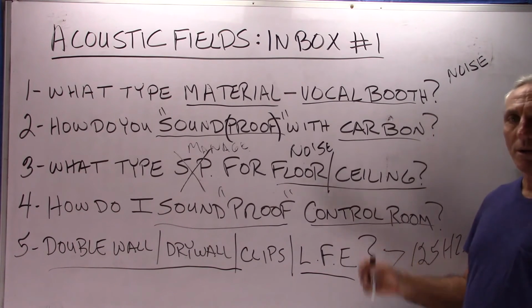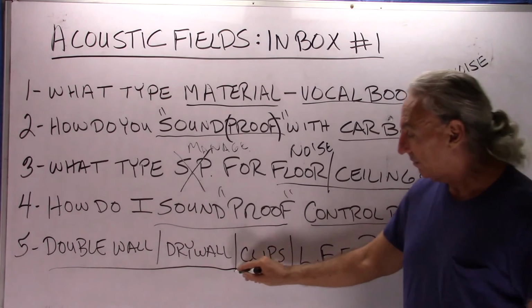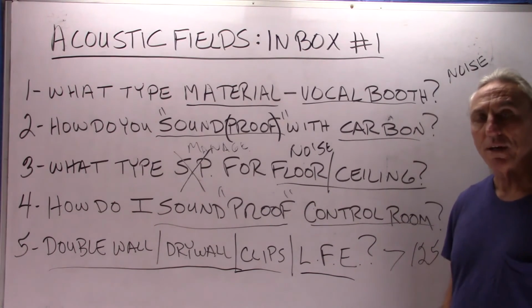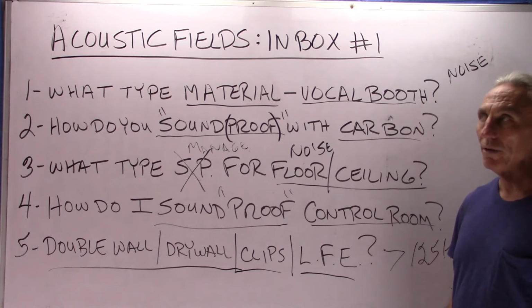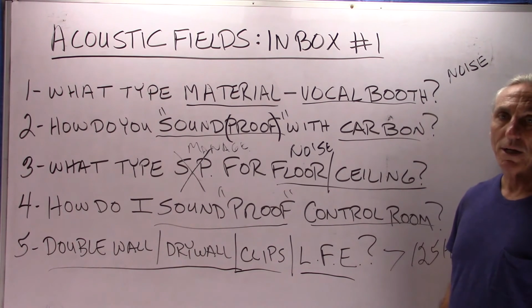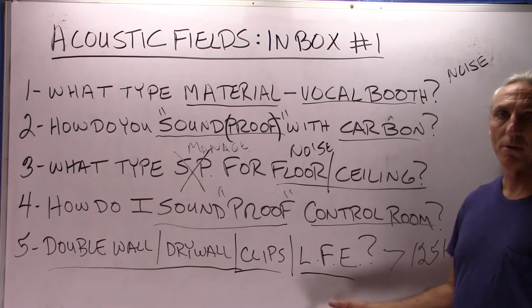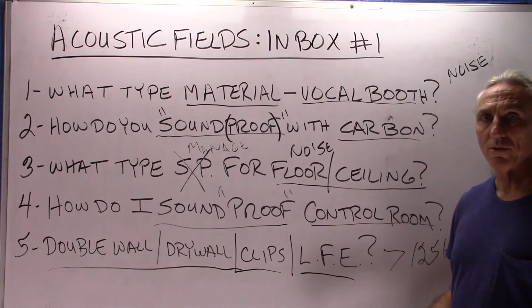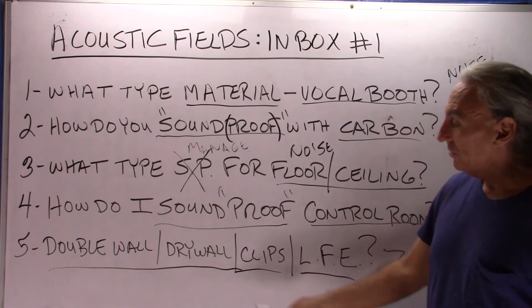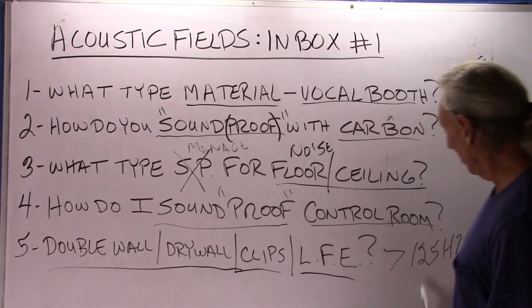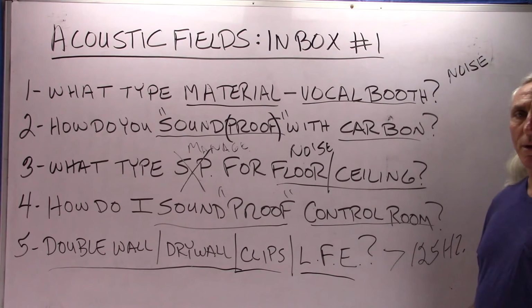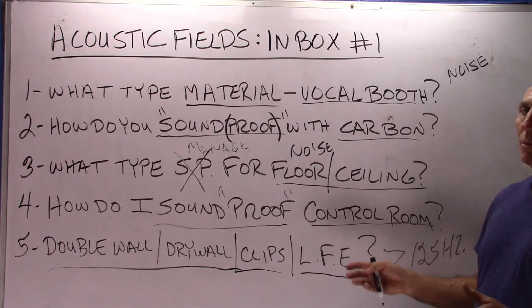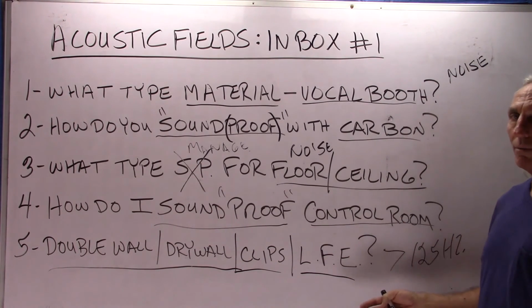So I have people call me all the time. Oh, I built my home theater using this. How many subwoofers do you have in the room? Four. Four 15s. How big is the room? Oh, it's average, 12 by 13, 8 foot tall. So it's a closet. And he's got four drivers that are 15 inches in diameter. And he used the technology that's only good for frequencies above 125 hertz. So do no harm. Remember, don't put too much energy in too small of a room.